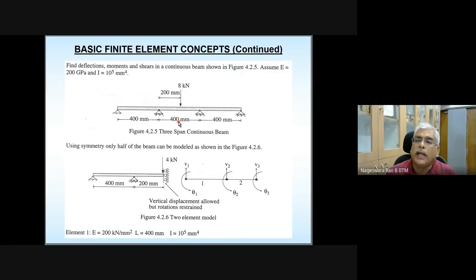If you want to take advantage of symmetry, you should be careful when you are applying the boundary conditions, because a symmetric boundary condition needs to be imposed on the plane of symmetry. If you are not sure about what symmetric boundary conditions you need to apply, then the best thing is to solve the entire problem without taking symmetry into account.